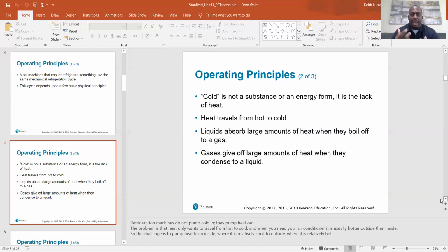The same air that's getting sucked out of the room through the intake duct or the return duct is being blown right back out through the supply ducts. But the only difference is before it comes out of the supply, all the heat is absorbed from it, because the liquid that's in that evap coil boils and absorbs the heat from all the air that's going across that coil.